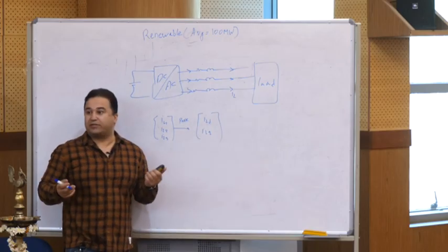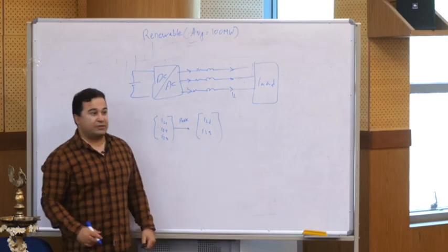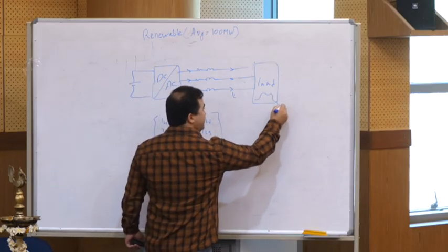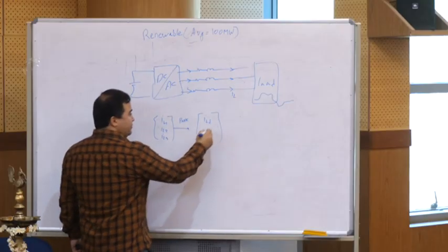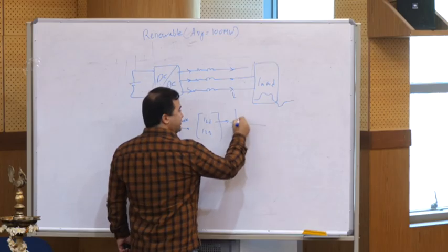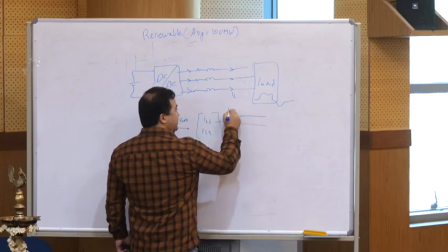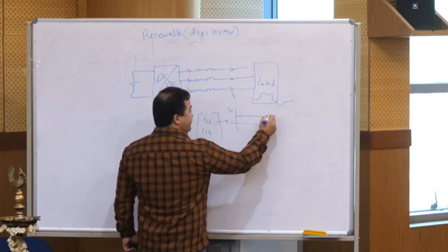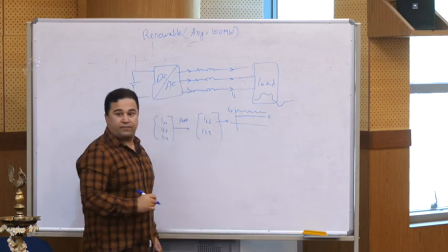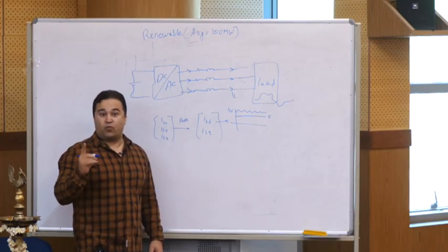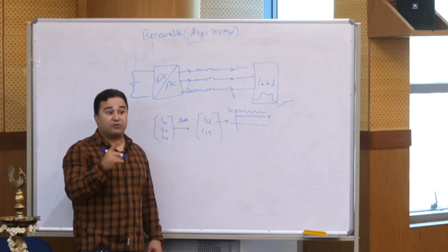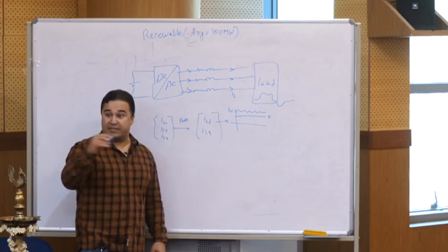Up to here is just a transformation. Then I say that my load is nonlinear, so it can be split into 2 parts. If I draw this one, ILD can be the fundamental frequency and harmonic. When we change from ABC to DQ, the fundamental frequency in DQ will be a DC value.